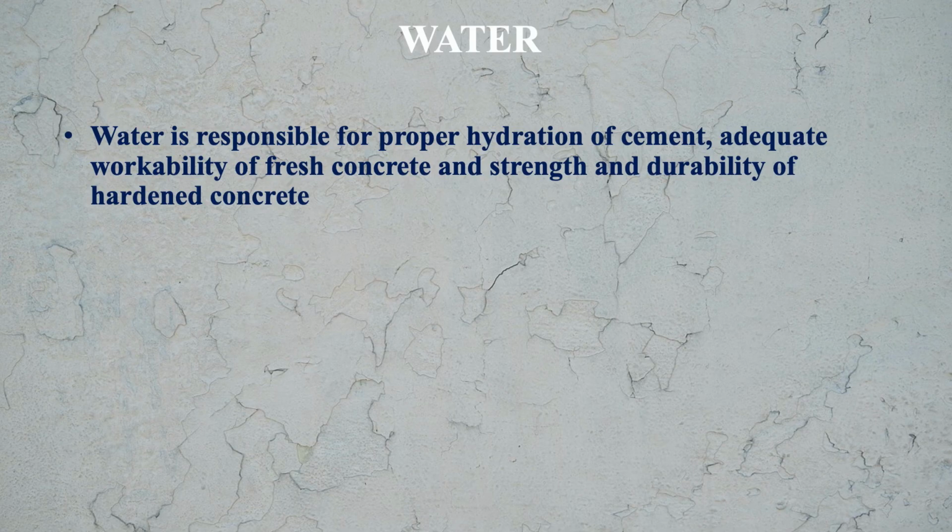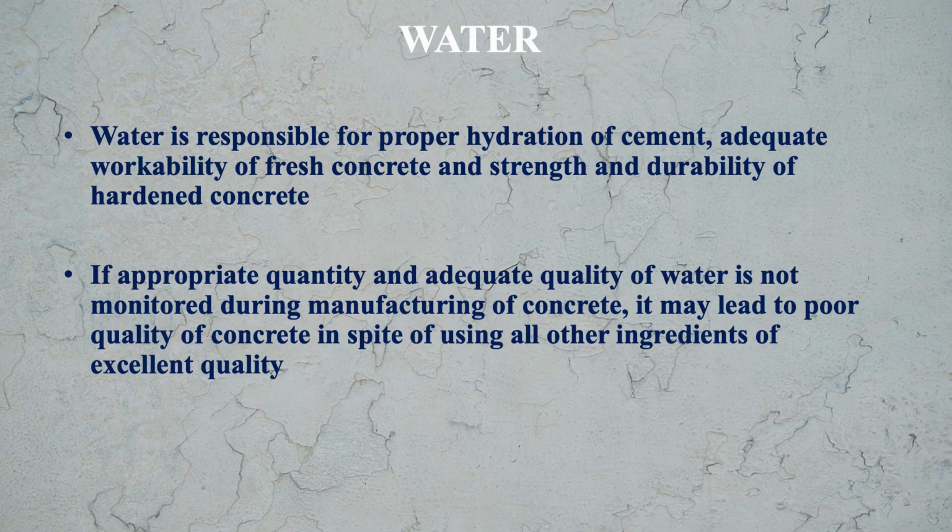Water is responsible for proper hydration of cement. It brings in adequate workability of fresh concrete and also strength and durability of hardened concrete. So water is governing all these properties of concrete in both the stages, in plastic stage as well as in hardened stage. If appropriate quantity and adequate quality of water is not monitored during manufacturing of concrete, what may happen?